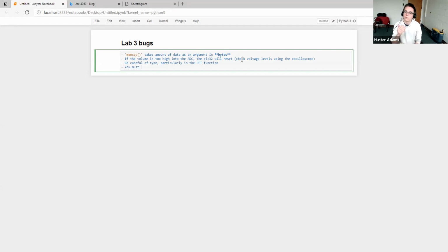For the spectrogram, just remember that the magnitude does not map to a coordinate, it maps to a color. So you'll move incrementally across the screen, so for a particular update of the spectrogram, all of your x coordinates are the same. In the next update, they increment by 1, you move to the next pixel. Your y coordinate will be essentially just the index of the output array, because that maps to frequency. And then the color of the pixel is related to magnitude. So you must change the drawing code in the FFT example.